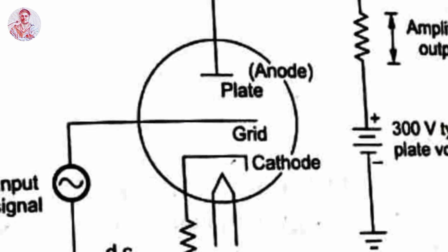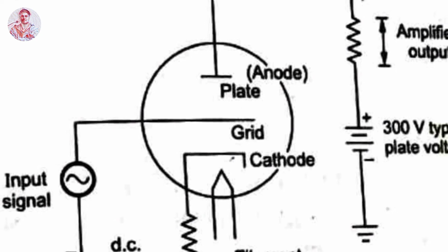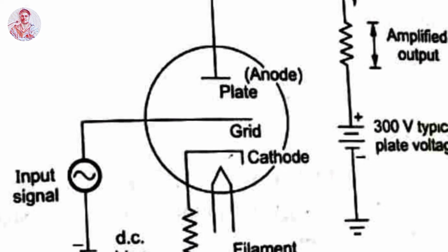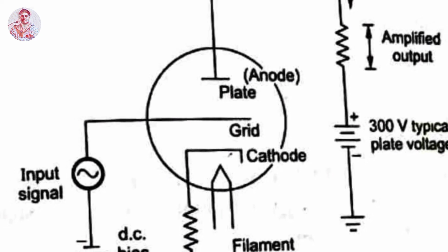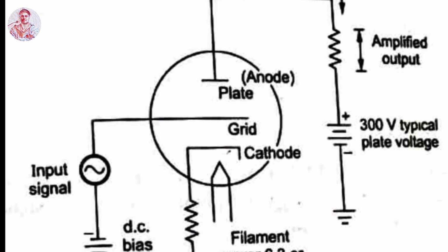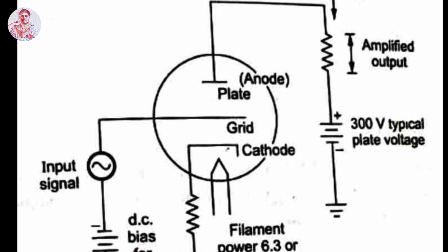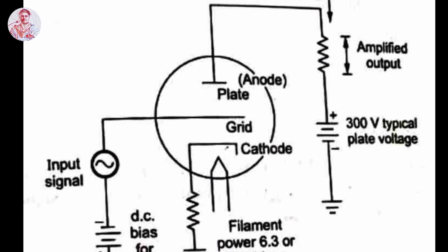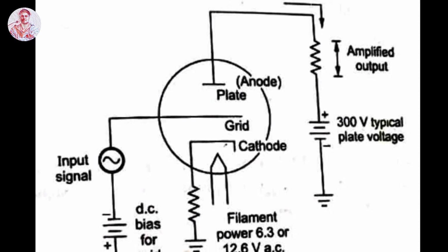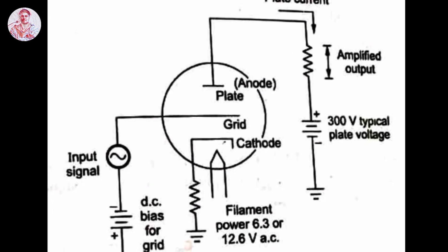Due to the flow of electrons between the cathode and anode, the plate current gets generated and the amplified output is produced across the load. The load may be an antenna, filter, or modulated or demodulated circuit. The intermediate component between the cathode and anode plates is the grid, which is used to control the flow of electrons by varying the voltage. When the grid voltage is varied from 0 to negative, then the large flow of electrons between cathode and anode is controlled and modulated.